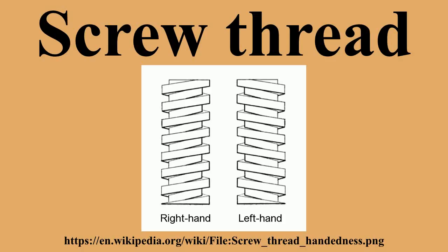The large torque at start-up should tend to tighten the nut. Also in combination with right-hand threads in turnbuckles and clamping studs, and in some gas supply connections to prevent dangerous misconnections. For example, in gas welding, the flammable gas supply uses left-handed threads.